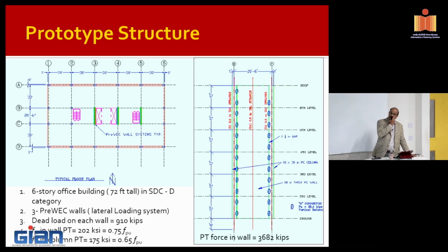Some of the pictures I've shown you from the Northridge earthquake in '94 are from when they tried to do it, and the unseating took place. Unseating took place, or 1 or 2 columns collapsed because they were not designed to take the load with the lateral movement, even though it's a free movement. And due to the P-delta force generated, they ended up collapsing. So the moment you collapse some of the columns, in one of the parking structures, if you recall, some portion of the floor system collapsed.